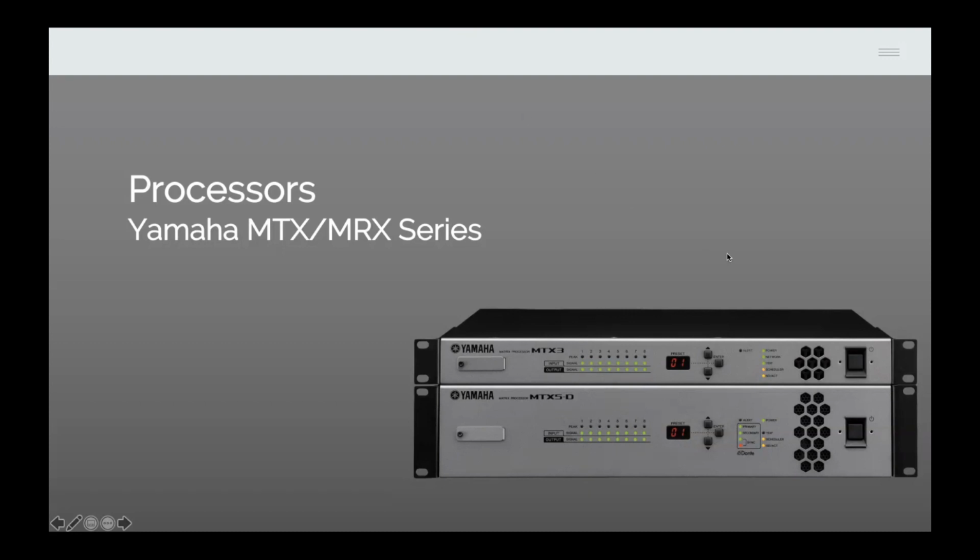I've just had a question in from Thomas. How would we run subs off these units? Would we run them in parallel, or would we run them on the 100 volt line? That's entirely dependent on how you want to do it. So in commercial applications, you have woofers and you have subwoofers. A woofer basically is a reinforcement of bass rather than the addition of lower frequency bass. So with a woofer, you would run that in parallel on the 100 volt line or on the low impedance line, as long as it allows you to.